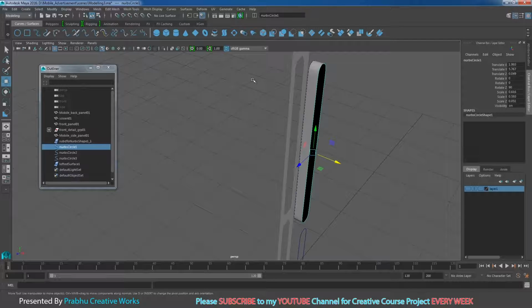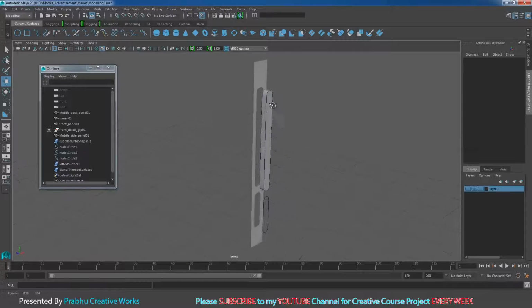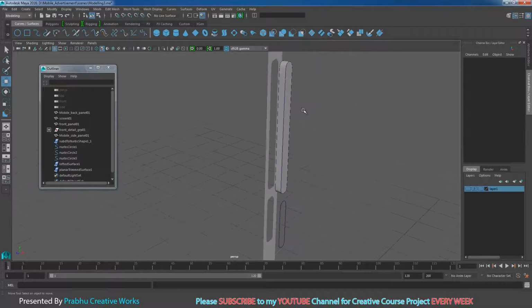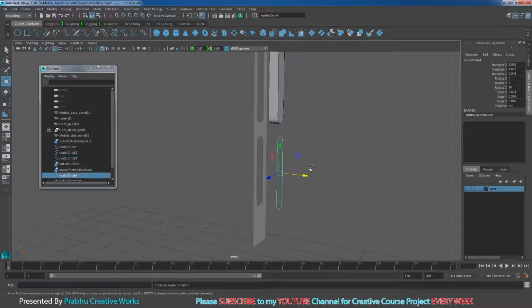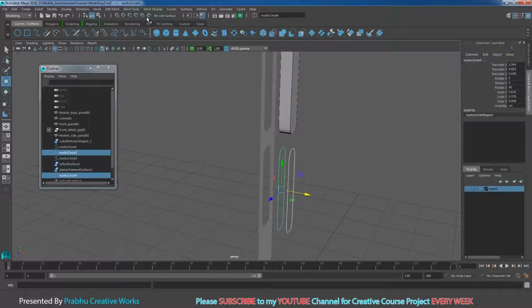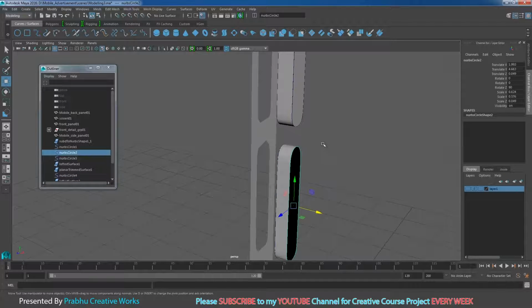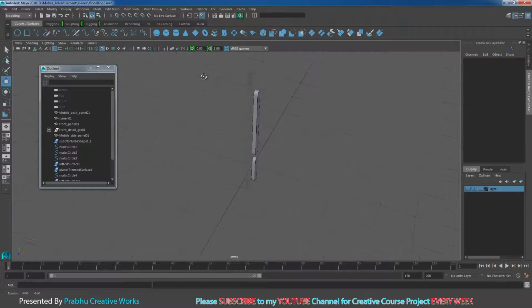Now you select this curve and go to surfaces and choose planar. That means your hole will be clean. Go to lighting and disable two-sided lighting. That means it will show the reverse lighting if you have problems. Now I select this curve and press Ctrl D. Now I want to move this one in X. I will select this one and shift select this one and go to surfaces and choose loft. Then I will select this curve and go to surfaces and choose planar. Now we got that button shape over here.